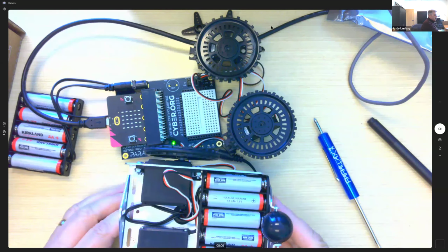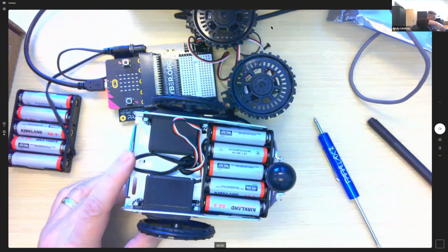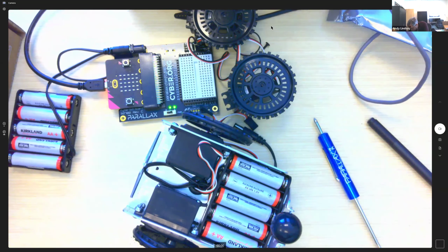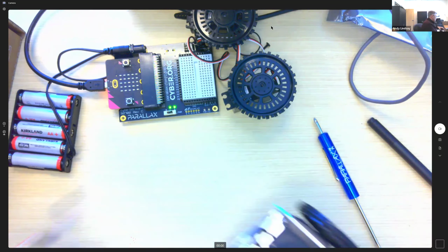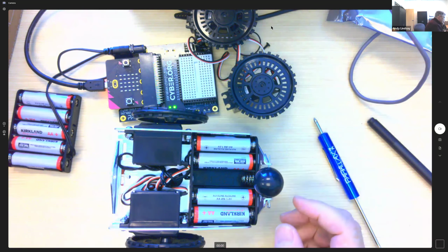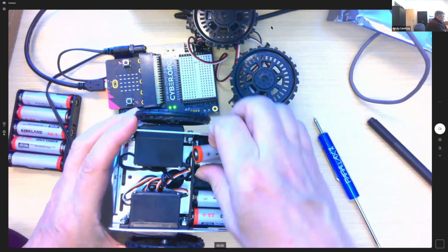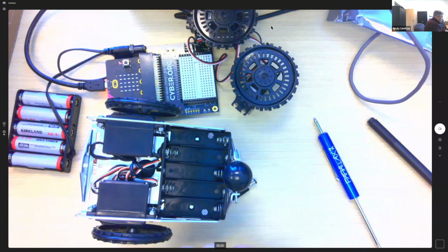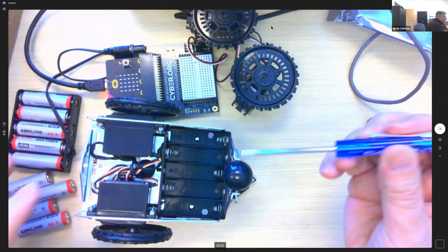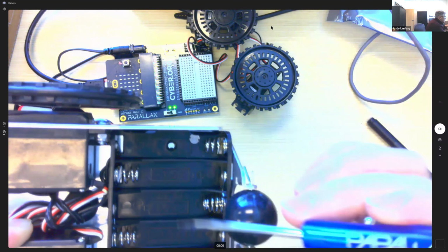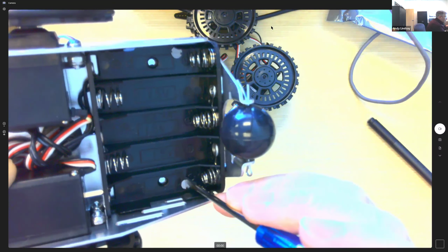okay, so here is an assembled robot. I want to get one that has servos that need to be centered. Yeah, here we go. All right, so the way to get at these servos to center them is to take out the battery pack. You'll pull out the batteries, and then you'll unscrew these two screws. There's two little white nylon screws that are holding the battery pack in.